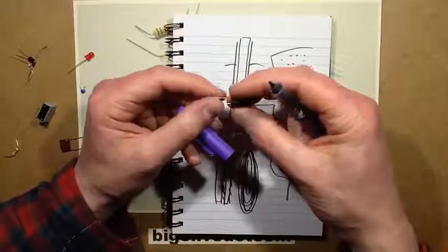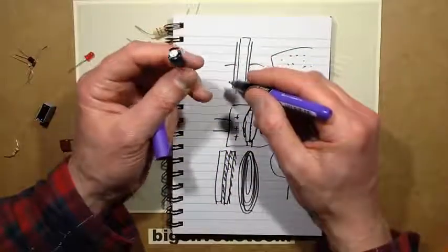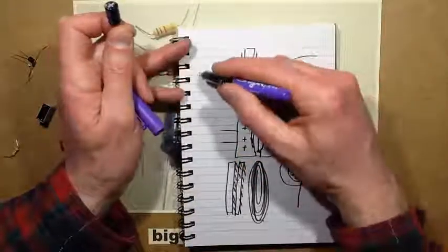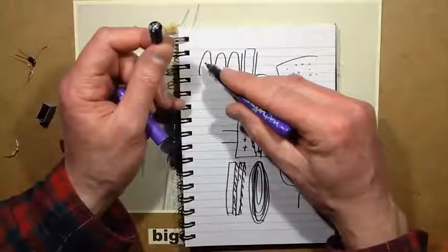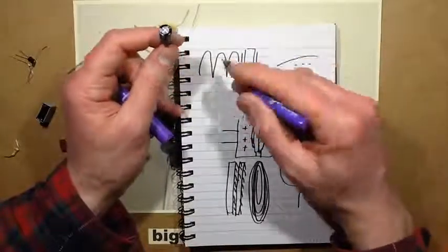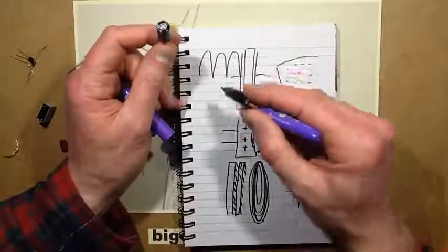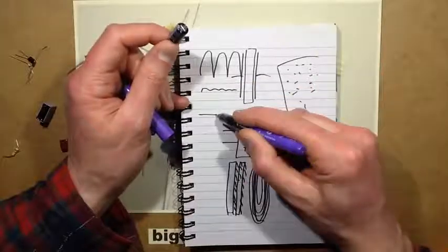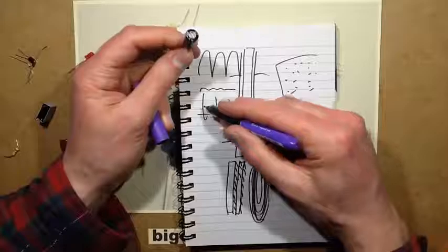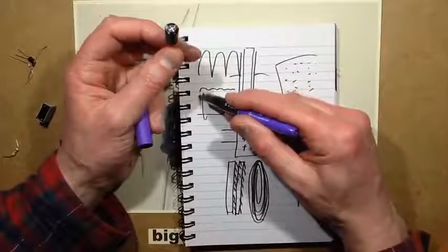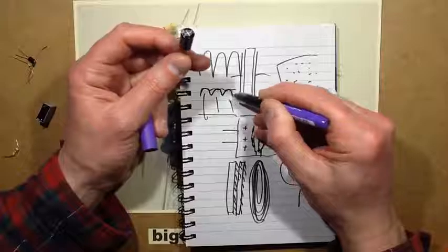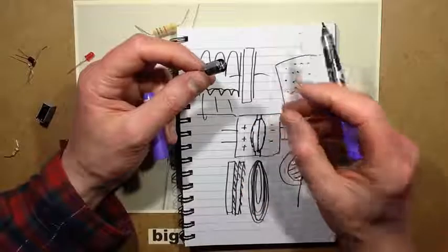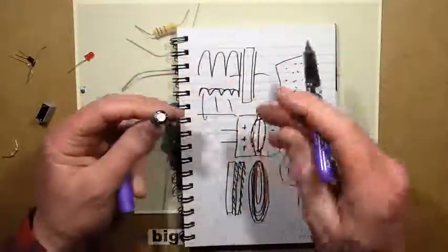When you get the large values like this, they're usually used to smooth ripples. So say for instance the output from the mains was rectified, and you had a big peaky full wave rectified AC waveform, which is like the two sides of a sine wave. Then by putting this across that, it reduces it to a very slight ripple and a nice smooth DC voltage. And as that capacitor dries out over time, that ripple will get bigger, and it ultimately starts causing problems when it dips down so low that the electronics can't sustain normal operation. And that's when you have to change capacitors.